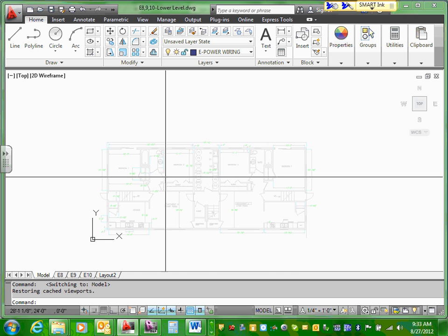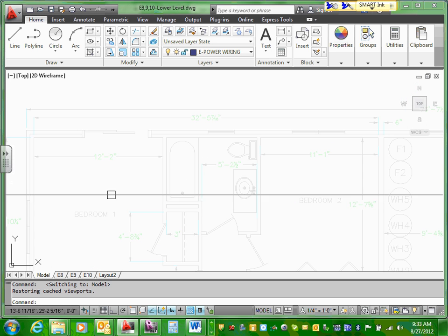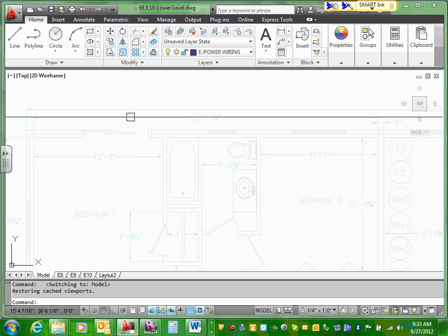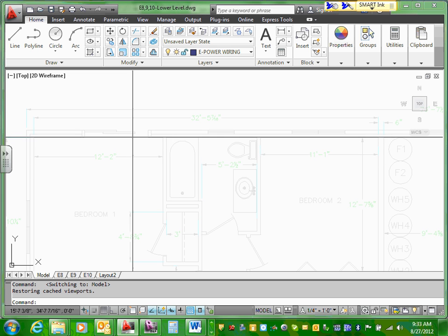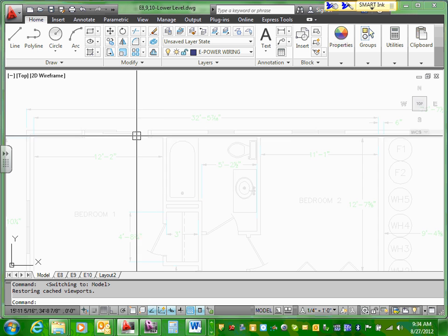Now, the last thing I want to do, guys, let's go drop. I'm going to go grab this. I want to remind you guys the lower apartments also have an entrance to the outside. Can you guys see that the lower apartment has an entrance to the outside here? So what does that by code require you to do? One GFCI from the apartment, in addition to what I'm required to. I'm requiring another two. That's my requirement. Outside. So be aware of that one.